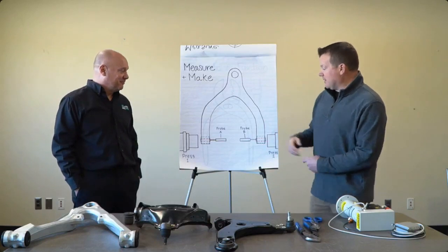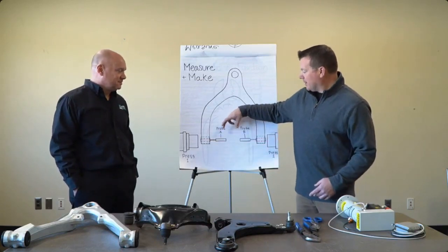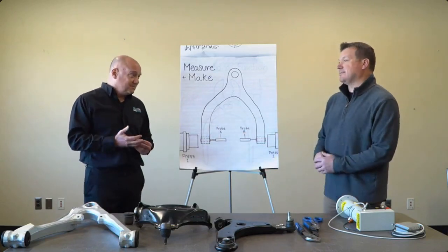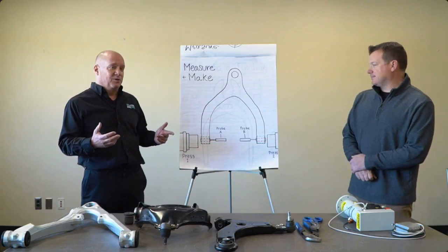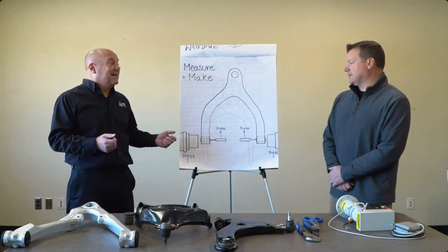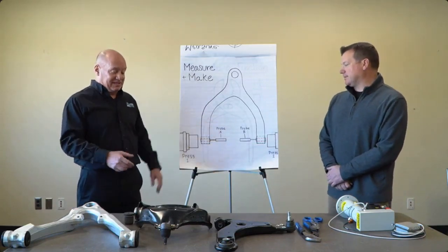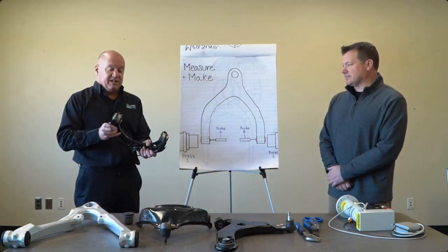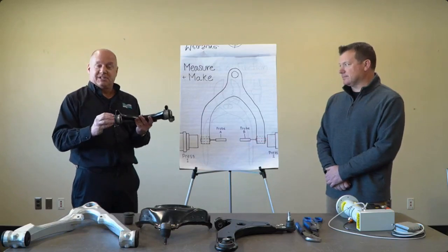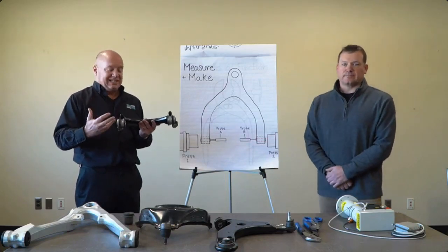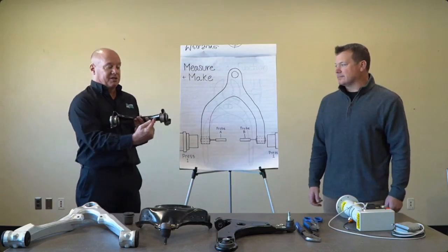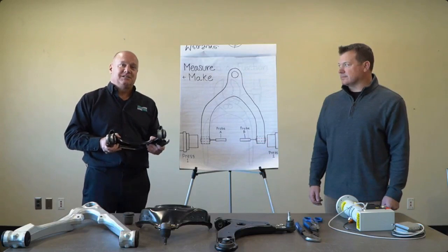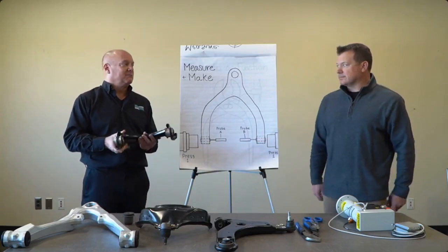So basically designing your fixturing is the hard part. Designing that so that you're measuring the right surfaces and that it measures it the same every time. Yeah, it's the old cliche, garbage in, garbage out. The key thing to being successful in an application like this, and where we've seen the difficulty, the controlling of the position is easy. All of this is an easy operation if you're getting good information. So the machine, the station, has to really be designed to be a gauge first and an assembly station after.